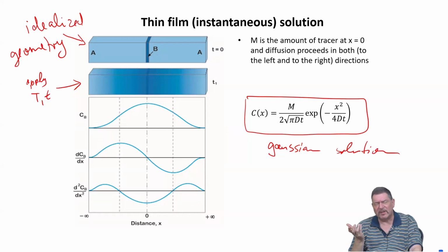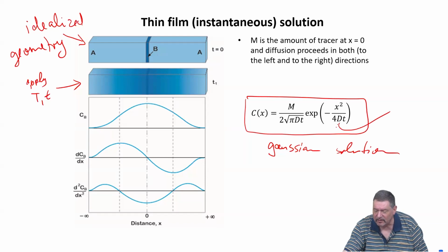In most cases in research we apply this type of diffusion measurement. We have a very thin source for the diffuser, which is not constant in composition, but is so few that it goes down in concentration, and then we get these very nice diffusion profiles. And then we can describe the composition profile by this equation, and what one really wants to get is this guy, right?